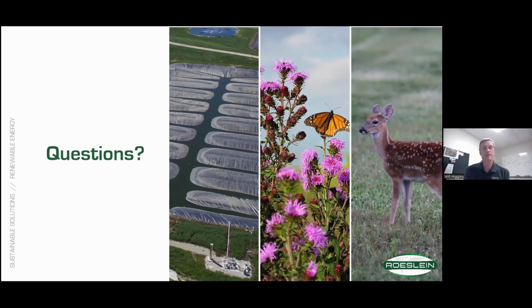Yeah, we've done a project in southern Iowa, and we have actually two lagoon digesters in southern Wisconsin, so not quite to Minnesota yet. But I would think the main concern is temperature profile. The winters there are much longer, so you would have a much shorter, I'll say, active season for the microbes. It might not start until middle or end of May, and then it's going to get colder sooner.